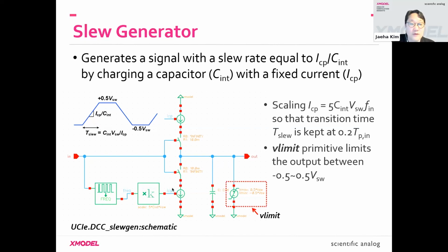Well, one way of doing that, you take the control code again and adjust the charge pump current over here. That's probably the implementation friendly way. The one way we have done in this model is we pretended that we have a way of measuring the frequency of the clock and then scale the charge pump current proportionally.